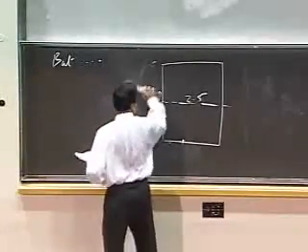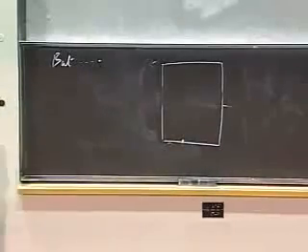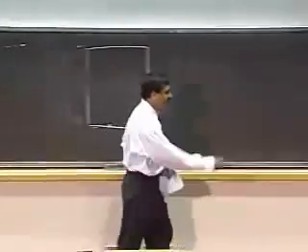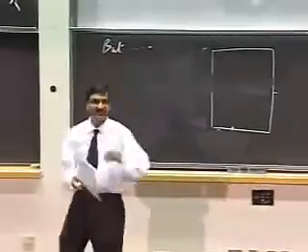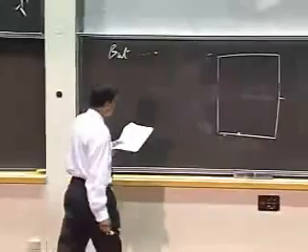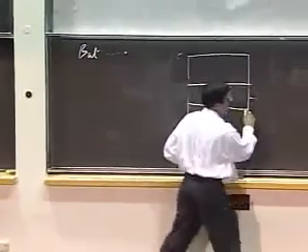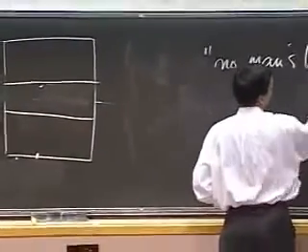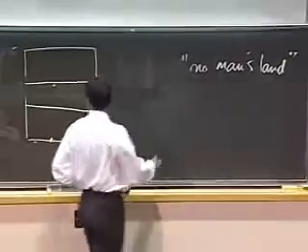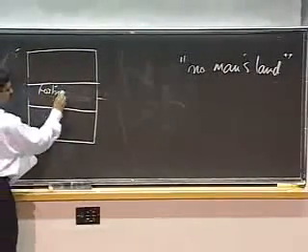Switch to page 7. So what I'll do here is, to prevent the receiver from getting confused if it saw 2.5, define what is called no man's land. I'm going to define a region of my voltage space called the forbidden region.